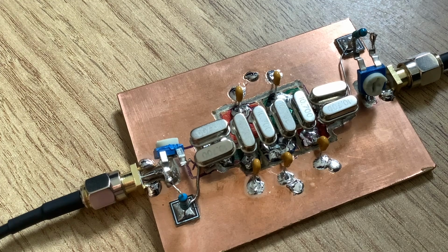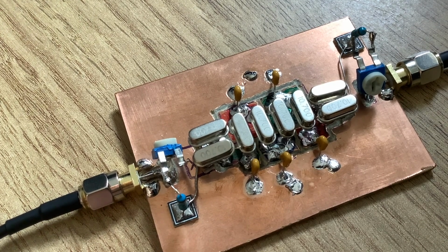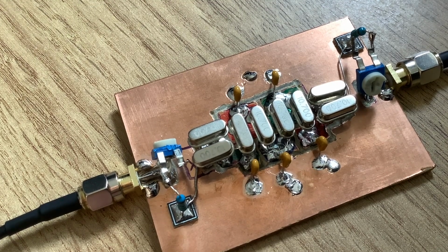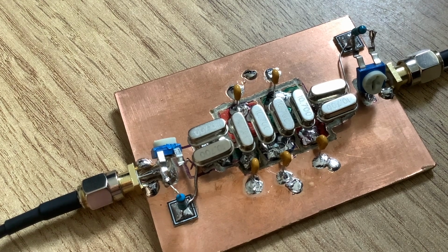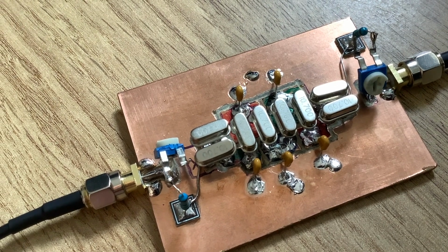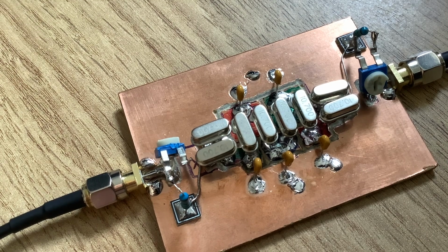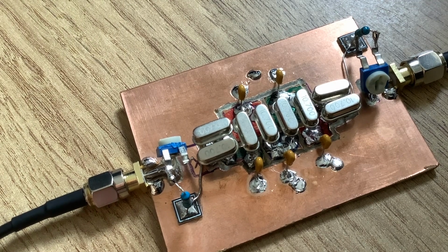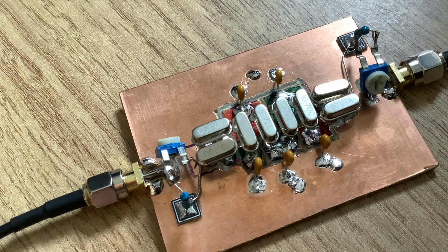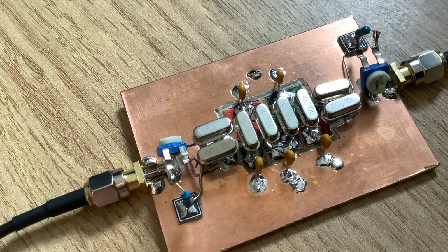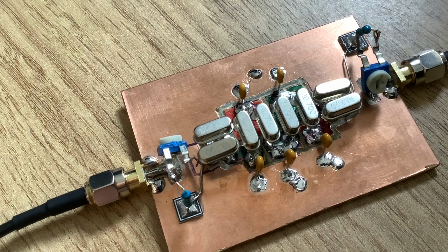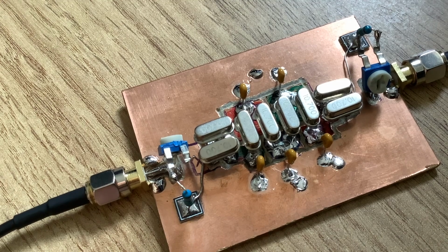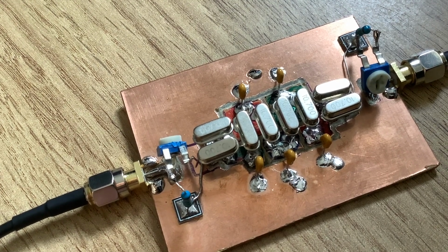So just a little status report. This is the board now. Now, full disclosure, I've completely replaced the capacitors twice at least, because the first time I put on 270 picofarads, which gave me an incredible filter, but it was so narrow. I mean, it was too narrow even for CW. It was really, really narrow. And I'd forgotten the fact with Cohn filters that the higher the level of capacitance, the narrower the filter. And usually I'm building SSB filters and I want a fairly narrow filter. But this time I'm not.